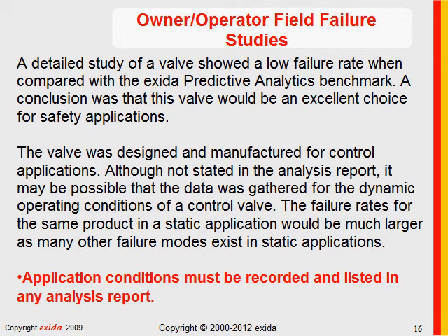In a control application, a mechanical product is somewhat dynamic. It's moving. In a low-demand safety application, such mechanical products may be static, motionless, for perhaps years. Then, the failure rates will be much different. The failure rates will be higher.